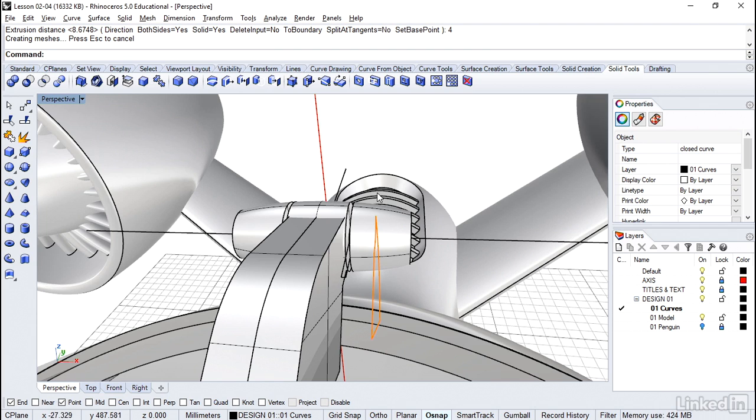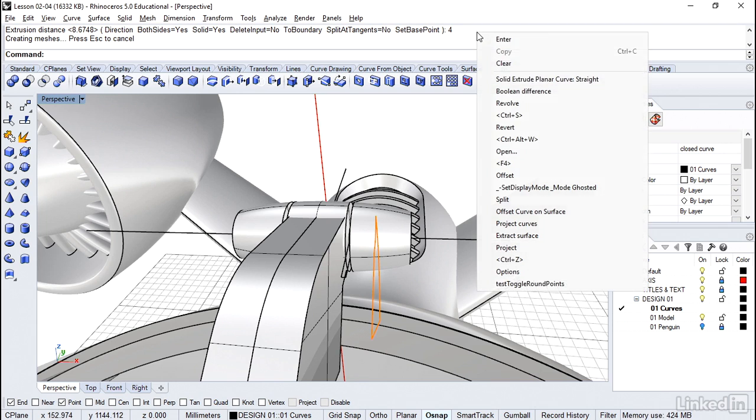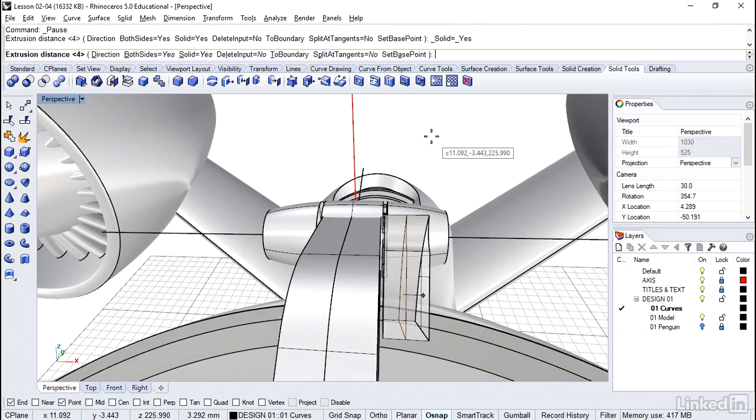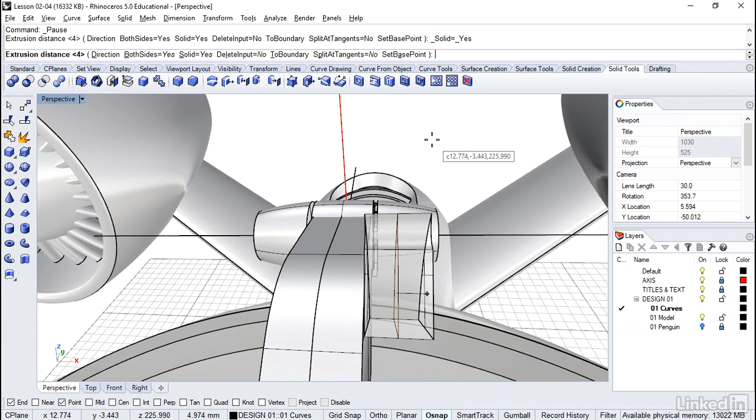Now to repeat the command, you can go up here in the command line and just right-click. There were the last 10 or 15 things we've done. So that's a great way to jump around if you're just doing the same couple of commands. This is a great shortcut to find things that were fairly recent. Okay, so this one, I've actually moved that curve around a little bit. We're going to have this be about half as much, so 2 each direction.